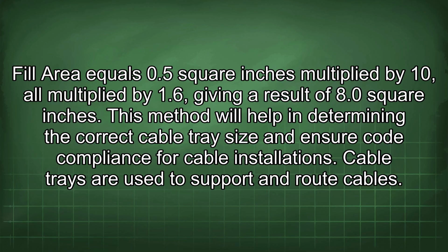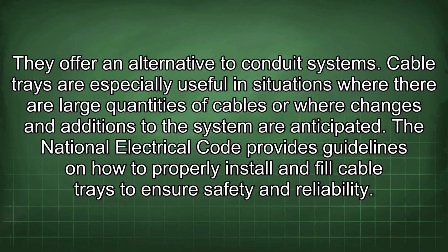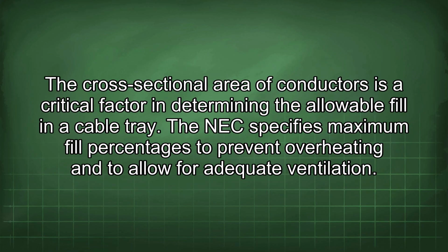Cable trays are used to support and route cables. They offer an alternative to conduit systems. Cable trays are especially useful in situations where there are large quantities of cables or where changes and additions to the system are anticipated. The National Electrical Code provides guidelines on how to properly install and fill cable trays to ensure safety and reliability.